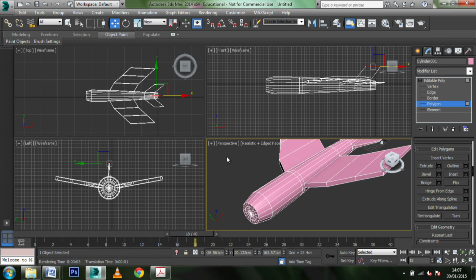So I'm going to keep the polygon selection on, and I'm just going to select 3 polygons on the very top. You can see there I've not actually managed to do that quite correctly, so I'm just going to deselect that one by holding the Alt button and clicking, and select this one there. And now I can see on the top left screen that I have got an even distribution of polygons. Then I'm going to select the bevel tool again,